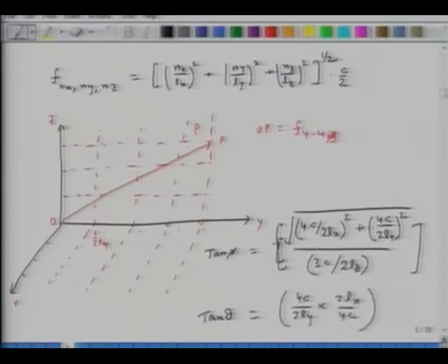So you have a process and an approach through which you can locate the physical nodes of different frequencies for a given 3D rectangular room. You find out its coordinates, and for each frequency, in a very methodical way, you can say that this is a node, this is a node, this is a node. So at the nodal lines, my pressure is minimum or maximum at the points where these intersections are happening. It's maximized, right? And my velocity is minimized. These node locations vary with respect to each frequency.